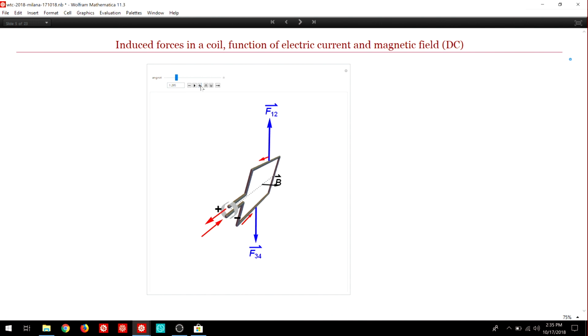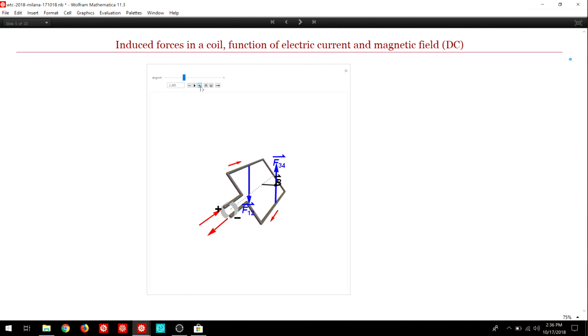And then for a DC machine, when it almost gets its equilibrium point, a commutator that is drawn here in gray. It was kind of difficult to make this using 3D because it's difficult to draw a part of a cylinder using this function, but I managed to make it. And then after the equilibrium point, inertia keeps it running, and so the commutator makes the coil touch the source in the opposite polarity, so current is reversed.